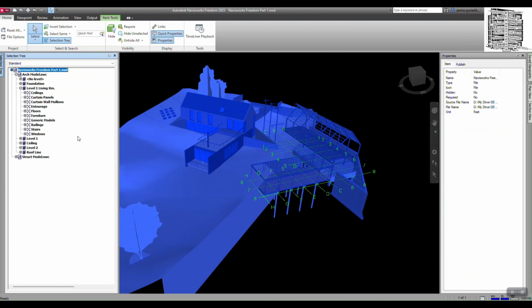So if you want to give an invert, you're gonna click on, let's say, the bottom of the pipe, and it's gonna give you the invert. And if you want to get the elevation between 2 points, this is a great tool to do so.